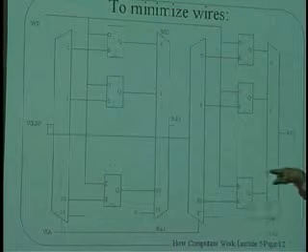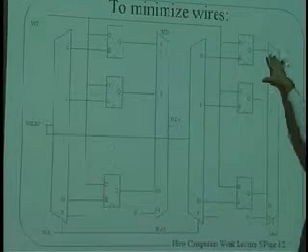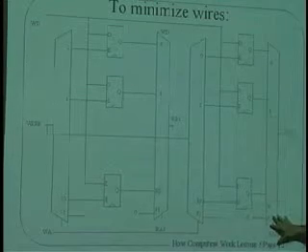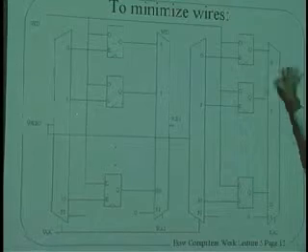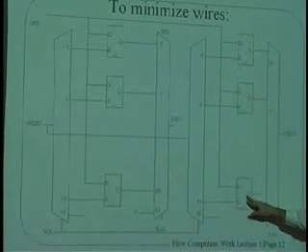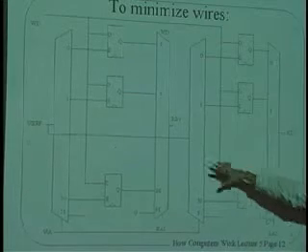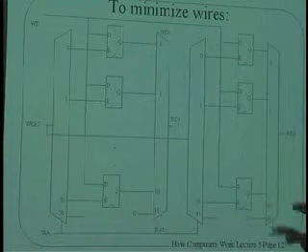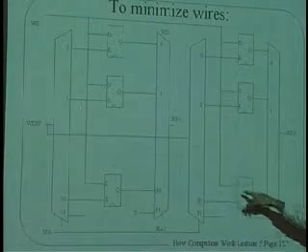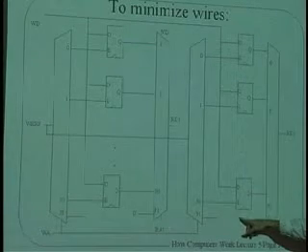Okay, this is this big tree structure that says, if it's one of these two bits, we choose these, then we choose these, we choose these. You get this huge tree here, and this one actually takes up most of the transistors on the chip, and this takes up very, very little. Okay, and the wires take up a lot of space too. And so it's actually sometimes more economical to build a structure that looks like this because it turns out that storage is cheap.